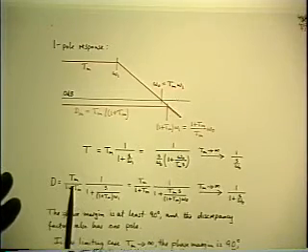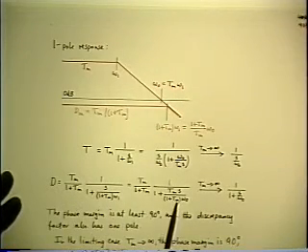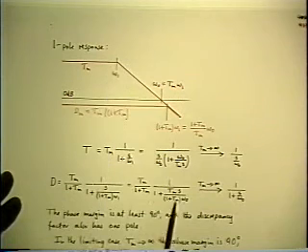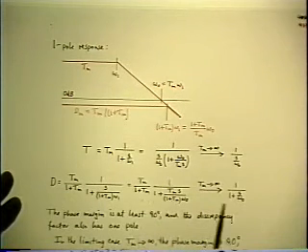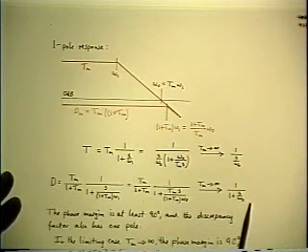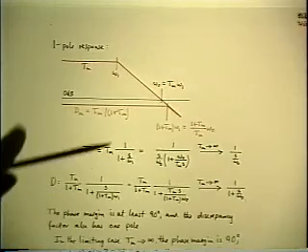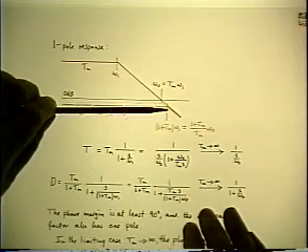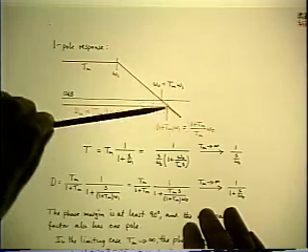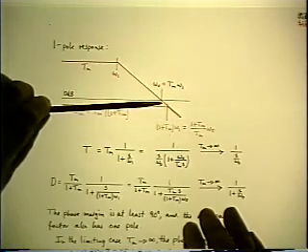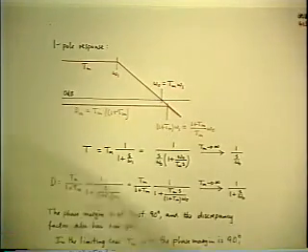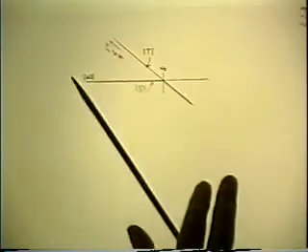At the same time, rewrite D to get rid of omega 1, and then let Tm go to infinity in that one, and you get 1 over 1 plus s over omega 0, which means that D has approached 0 dB and its corner frequency has approached omega 0. So the whole thing comes down to that.